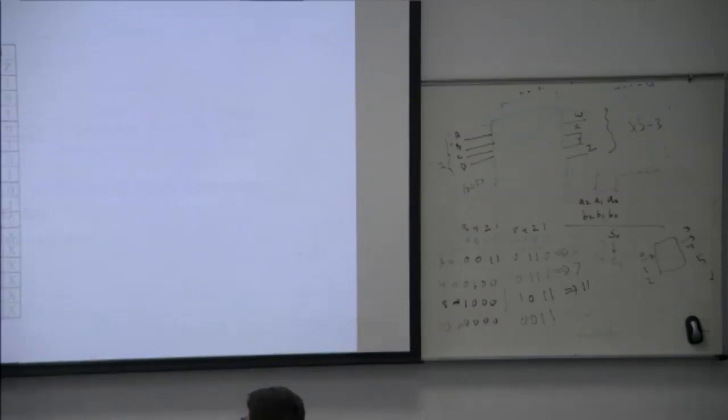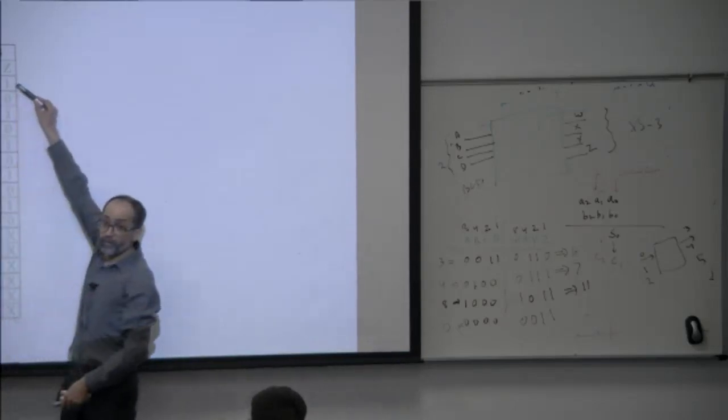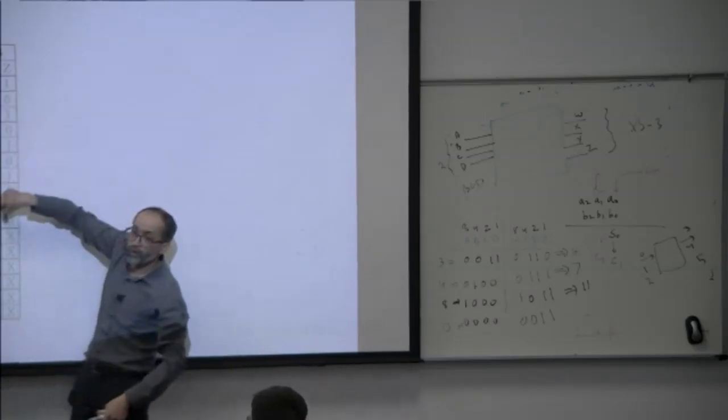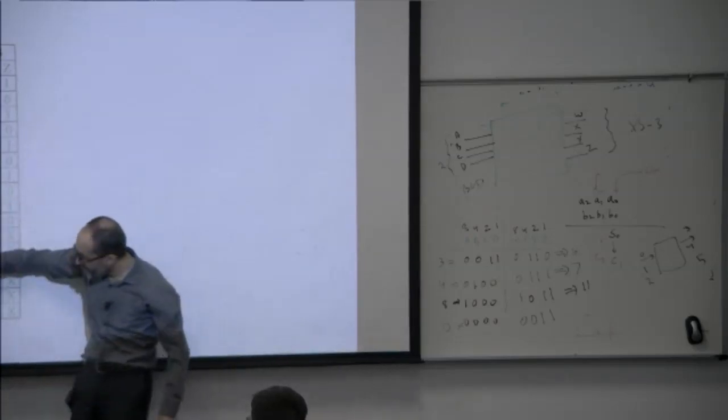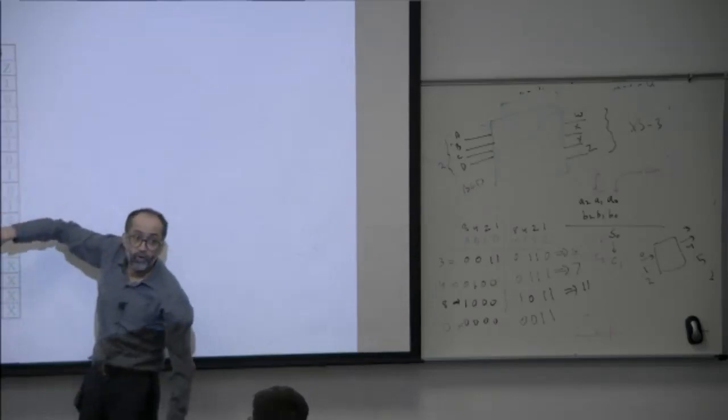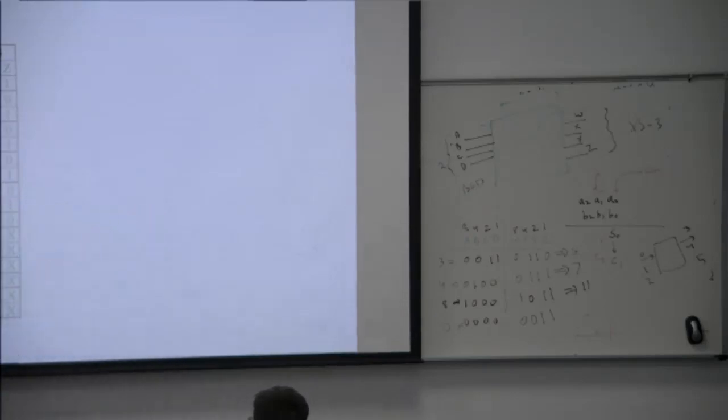So now, if you look at here, everyone, please compare it. This is the truth table. The input is 0, the output is 3. The input is 1, output is what? 4. Okay. Now this XS3 code starts from 3 to what? 12. And all of these last conditions? Don't care. These are all the don't care. So how many functions do we have? 4. So it means W should be a function of ABCD.